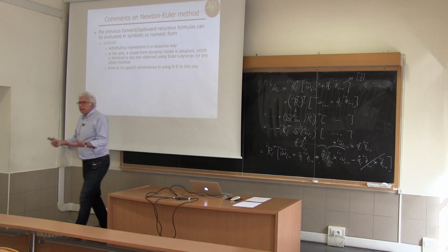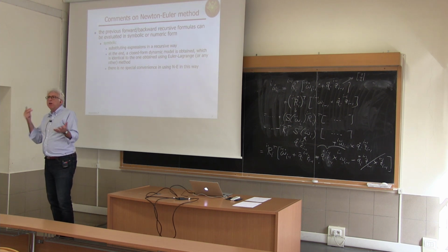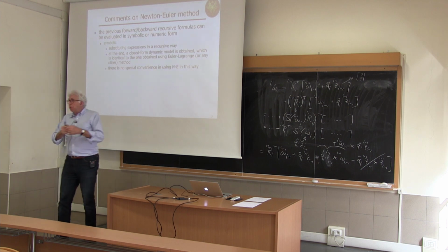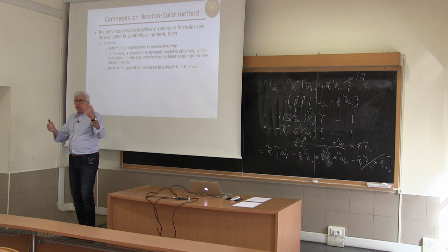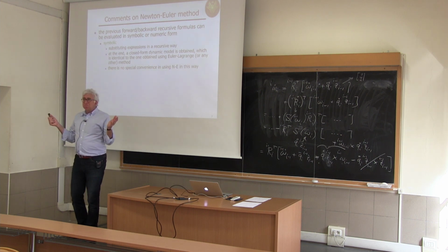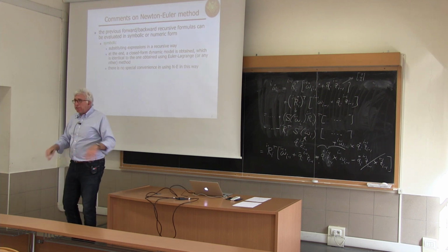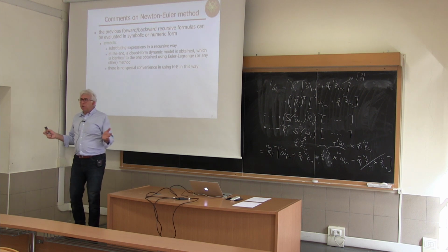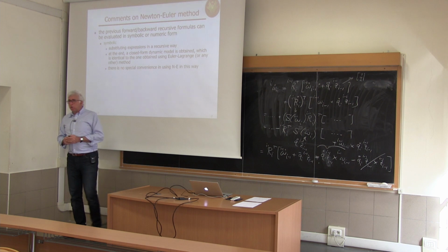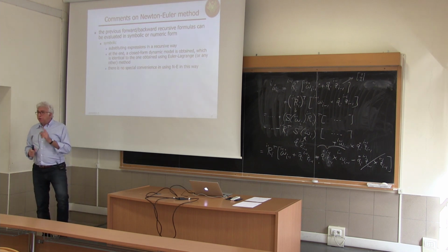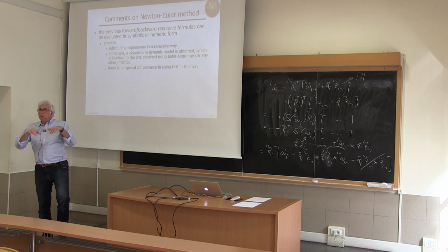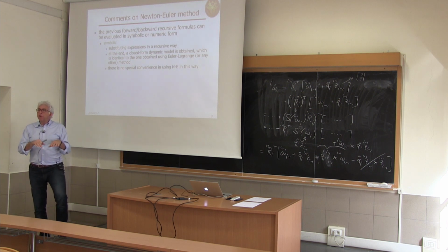Because otherwise, the system will fail to have data. And you don't know in advance which data will not be used, because if some of this data will not be used and you don't specify it, or you specify an arbitrary value, 0 or 10 to the 5th, no problem, because this data will never be used in the computation for that specific robot, and you have no problem. But you don't know this in advance. So in principle, you should provide all this information. And this is a critical point, because you know that you cannot identify those parameters in general. You can only identify dynamic coefficients, so combinations, which are those that appear explicitly in the Euler-Lagrange form. Those others will be relevant probably for the internal forces, but not for the forces producing motion.